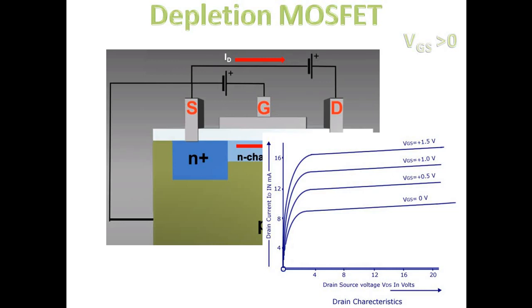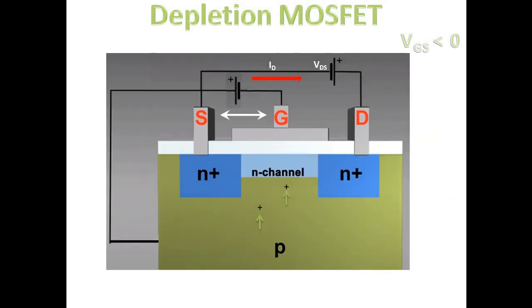So that is one side of the story where we have figured out what is the difference between JFETs and depletion MOSFETs, which are similar in working principle in quite a large number of parameters. Now let us look at the third side, the third story where we have VGS less than 0. So we discussed VGS equal to 0. We have discussed VGS greater than 0.